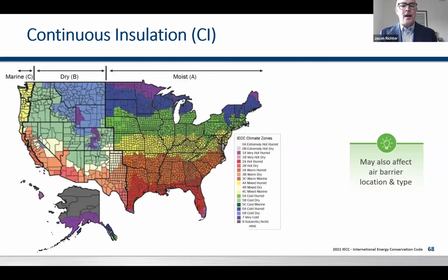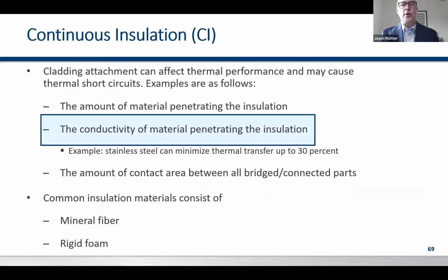handle your vapor barrier. Somewhere along the lines of zone, we'll say zone 3, you'll start to flip your weather resistant barrier from interior side of the insulation to exterior side. There, your goal is to keep as much moisture out of your insulation as possible to prevent mold buildup. But with continuous insulation, the devil is in the details, as they say.